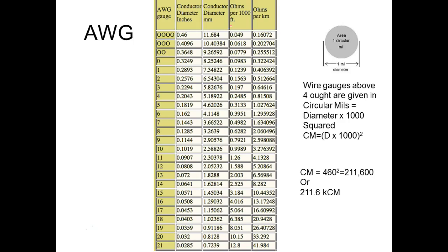So this is the American wire gauge. This shows you the wire number. And there's a formula, by the way, to figure out which number goes with which gauge. Basically, what you need to remember, the higher the gauge number, the smaller the wire. After a while, you'll learn it. So we deal with a lot of 14 gauge wire in our house, copper.